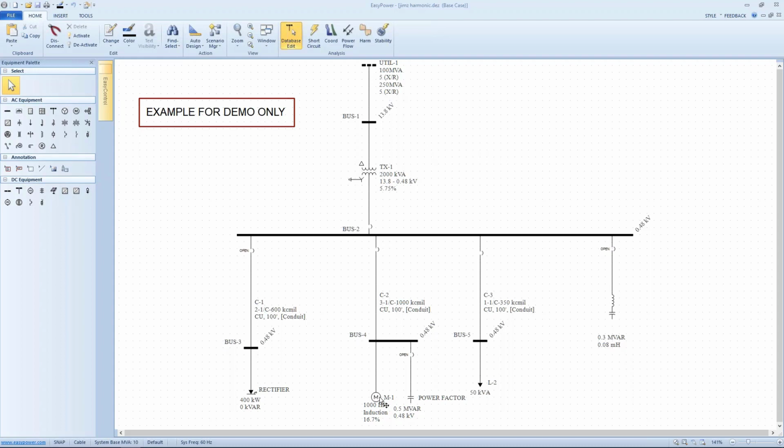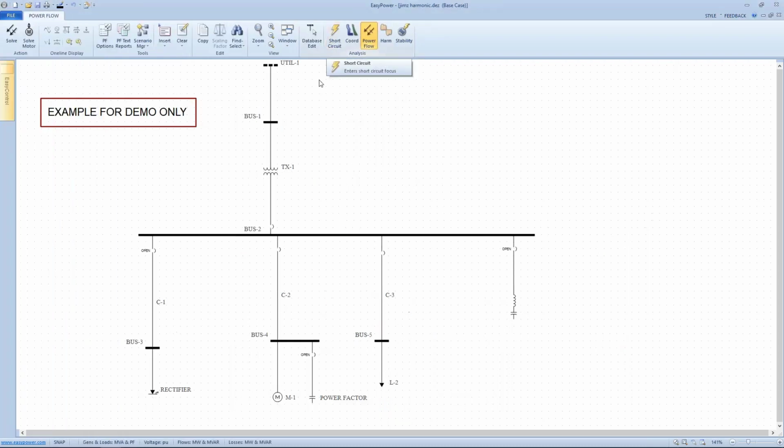And in particular, I've got a 1,000 horsepower motor on a 480 volt bus, not usually something you'll see in real life. But with that said, let me walk through the storyline that I just laid out. First of all, we have a one line diagram, and all of our loads, let's say, are linear. And so what we'd see as we go into power flow is the ability to solve for both the real power and reactive power demand.